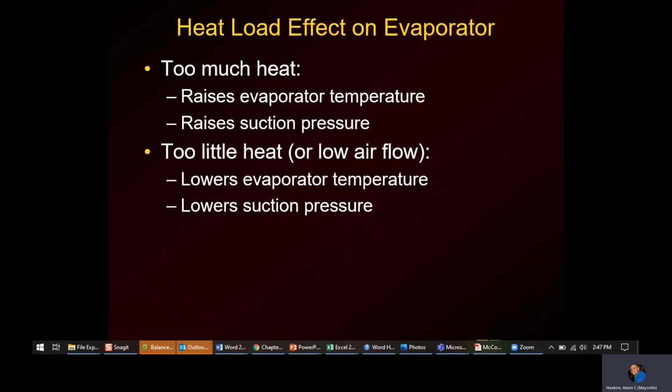So if you just say my gauges should always read 45 or always read 40, you're going to run more like 50 to 55 versus 40 to 45 on normal conditions. But if you just charge it to 40, then once that room gets pulled down, that's going to drop more, and now you're still going to be undercharged. So you've got to take all that into consideration.